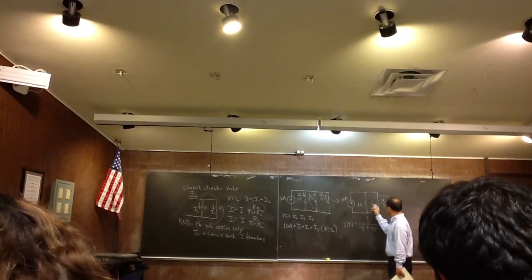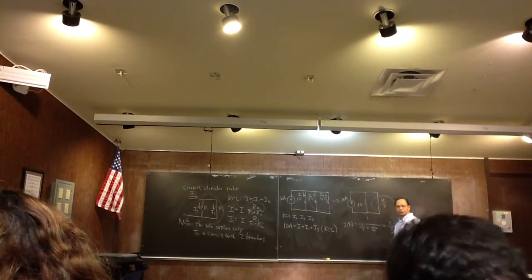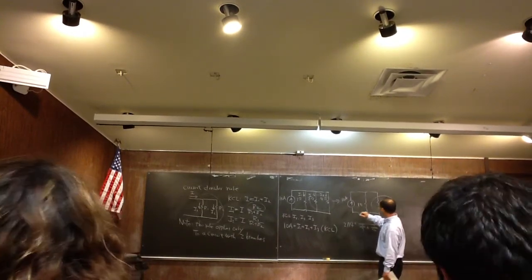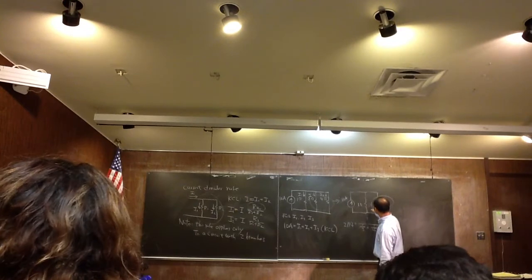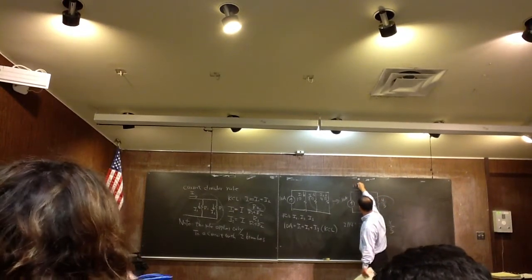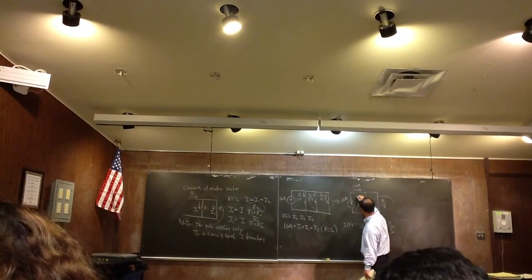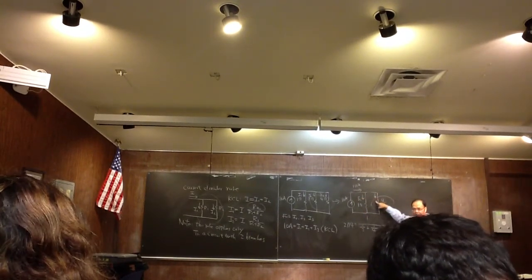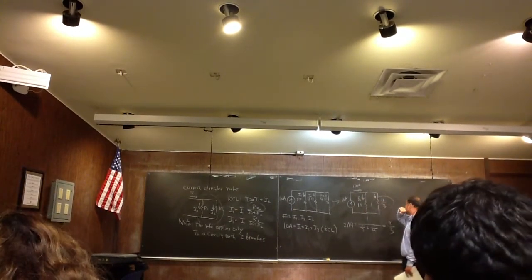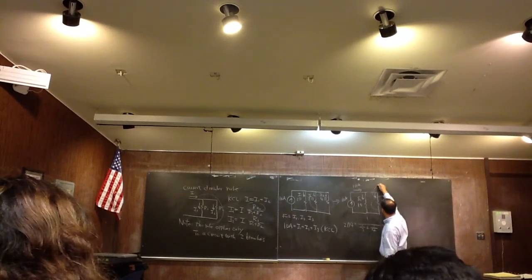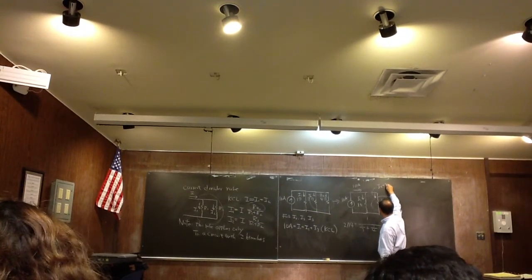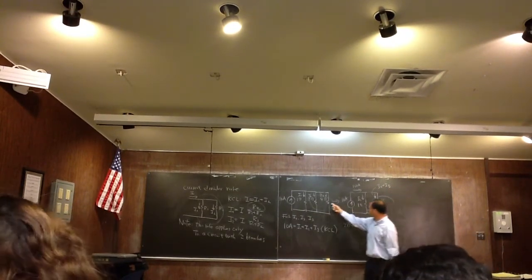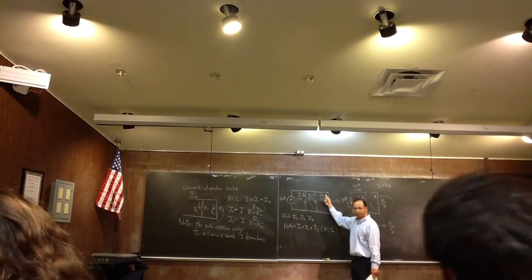Now we have a circuit with 2 branches of resistors. So now I can start to apply the current divider rule. So this is 10 amps, correct? Okay, so I'm going to call this still I1, but this is not I2 or I3 anymore, right? This becomes I2 plus I3. Why? Because if I combine these 2, then the currents must be added.